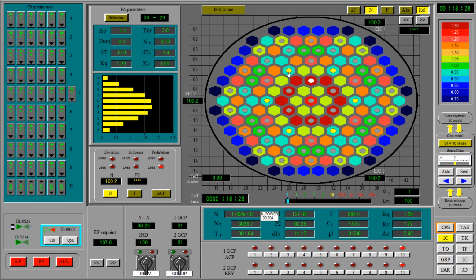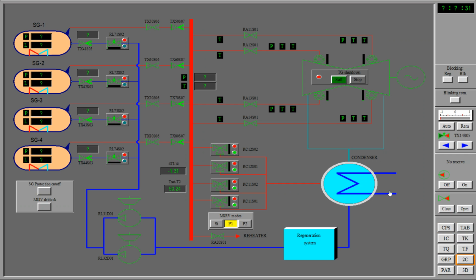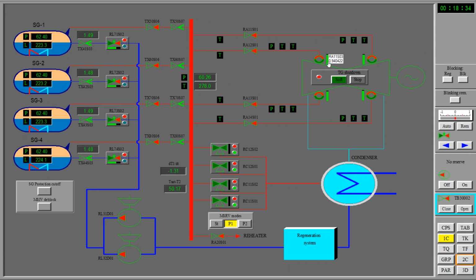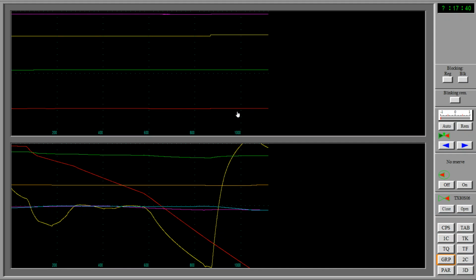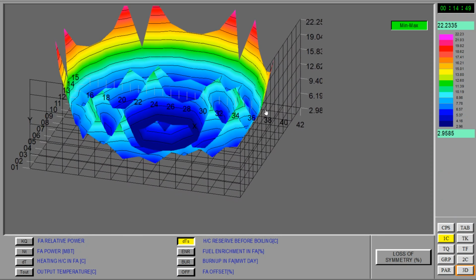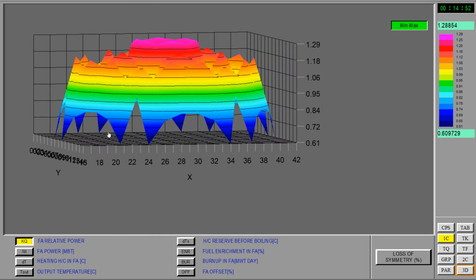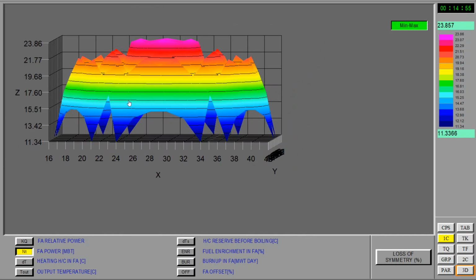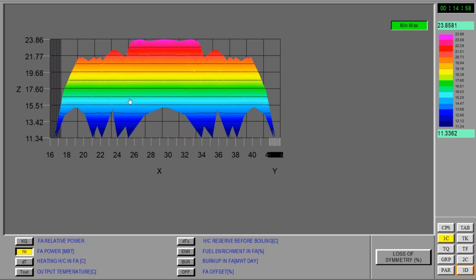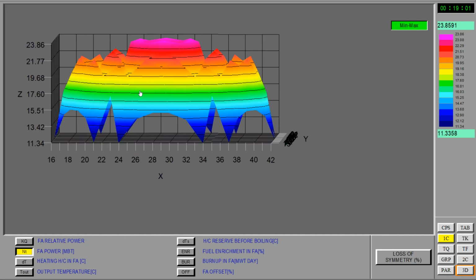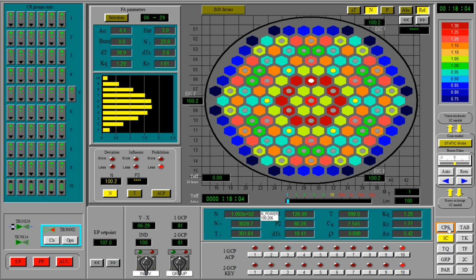Okay, we're at 3 degrees from boiling, very close now. Let's have a look into the secondary. Everything works totally fine. And everything looks fine also in the nominal values for power, neutrons, offset, and everything. Just look at the power. This is the relative in absolute values, still almost the same as when we wrote down values a few minutes ago. We're at 2 degrees from boiling. Very close now, reactivity is still 0.